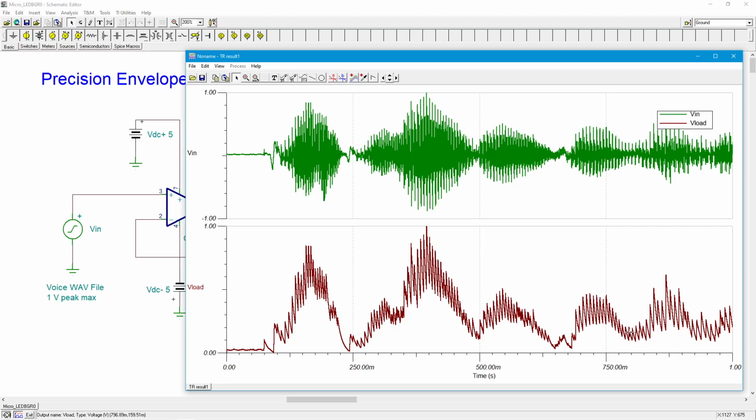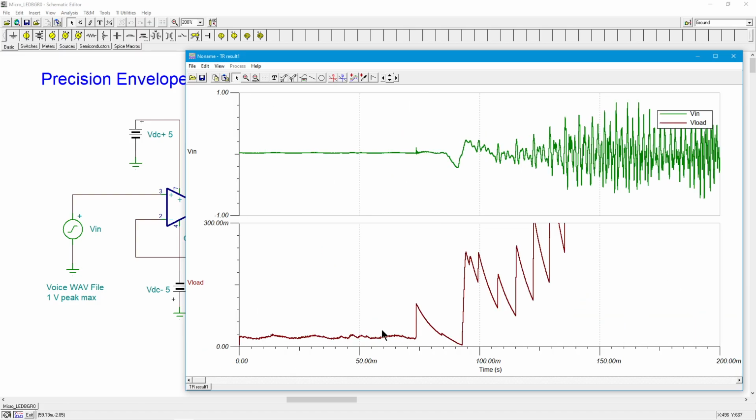You can see these sort of sharp little lines, and you can adjust this by the size of the cap. Some places it's kind of obvious what's going on, like right here. You can see that cap discharge. Matter of fact, we could sort of zoom in on this a little bit. All right, so that's the cap discharge coming in, on all of those things. And you can just compare that to what the input signal actually looks like. We have different scales, right? But this is essentially the positive piece of this. It's grabbing these things and sort of filling in the gaps, right? These spikes are these bigger ones, and then the cap is filling that in.